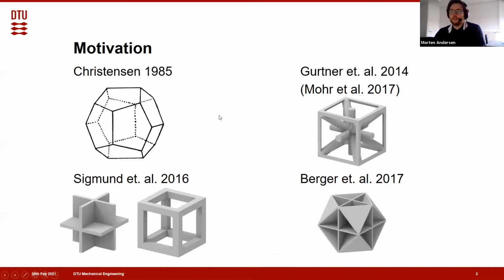But yeah, so we basically have a stiff competition going on for decades, where various microstructures have taken the place as stiffness optimal, isotropic stiffening optimal: this structure by Berger and this one by Gertner, this open wall truss lattice and the closed wall plate lattice, and then these orthotropic stiffness optimal lattices proposed by Sigmund and his team. But we have been missing a part of the discussion, which is the buckling strength.